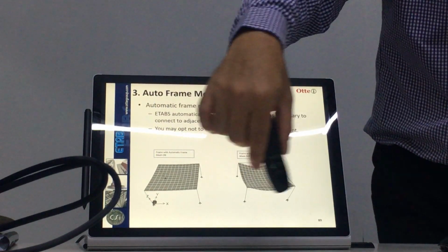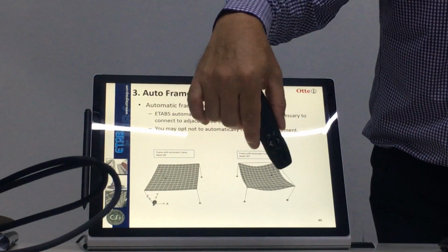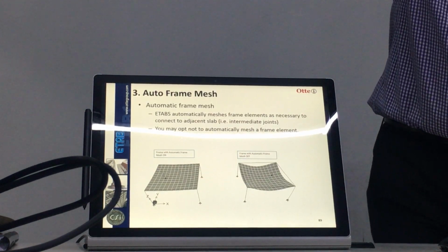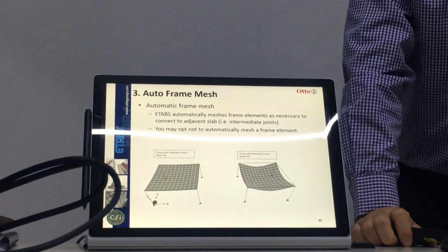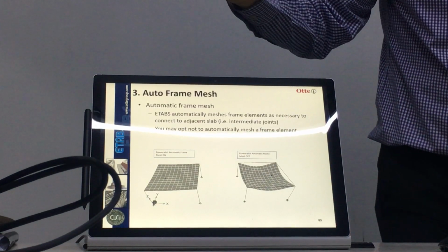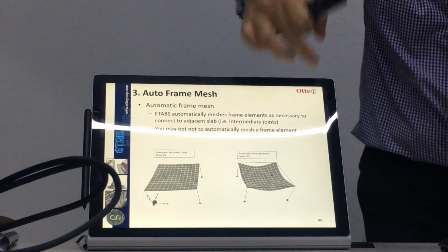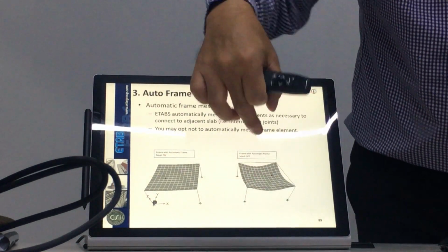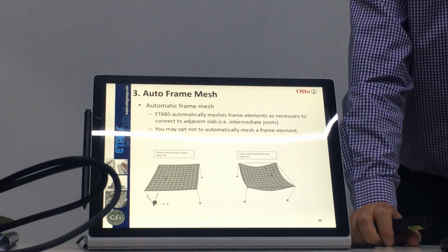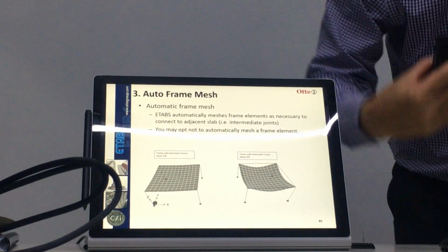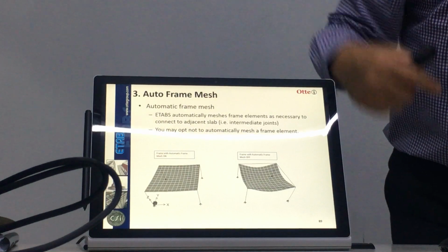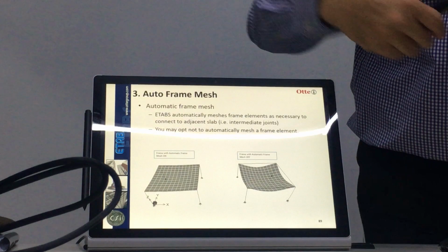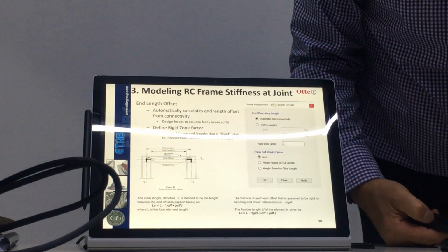But you have a steel structure, which is a car park. And on top of the steel structure, you have glass. The glass is only supported at four corners. So this captures the behavior of a steel gazebo where you have steel, but the glass is connected at four corners. You still have the stress in the glass because of the finite element, but the glass is only connected at four corners. So this is the correct model for your steel structure. That is how understanding what you're doing matters. If you do this with the beam-slab connection, you are using a wrong model to estimate the load. So that is important to understand.